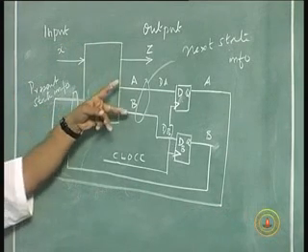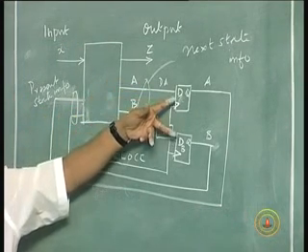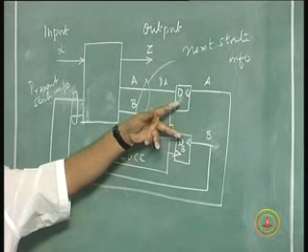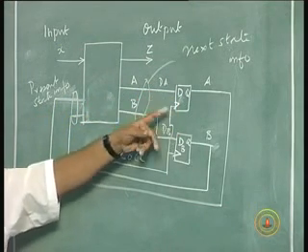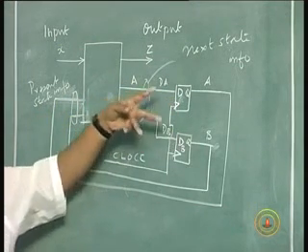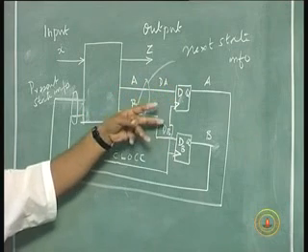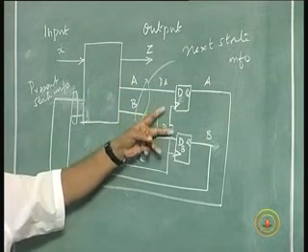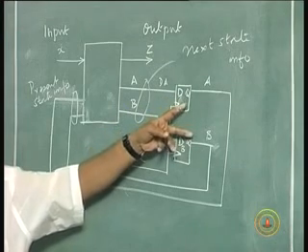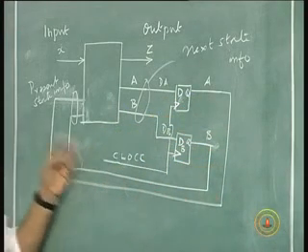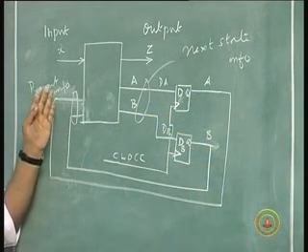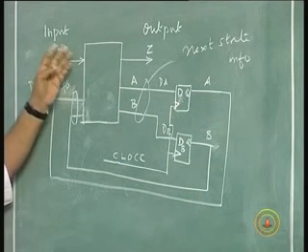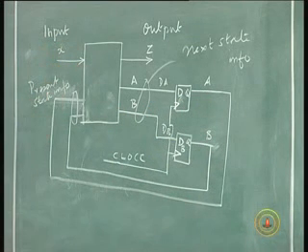But next state information becomes the next state by absorbing these values into this flip-flop, by storing these values in this flip-flop. That will happen at every clock. At the next clock, this becomes next state information. The next state information becomes the present state for the next cycle. And then that, corresponding with the input, will go and decide the third state and so forth.